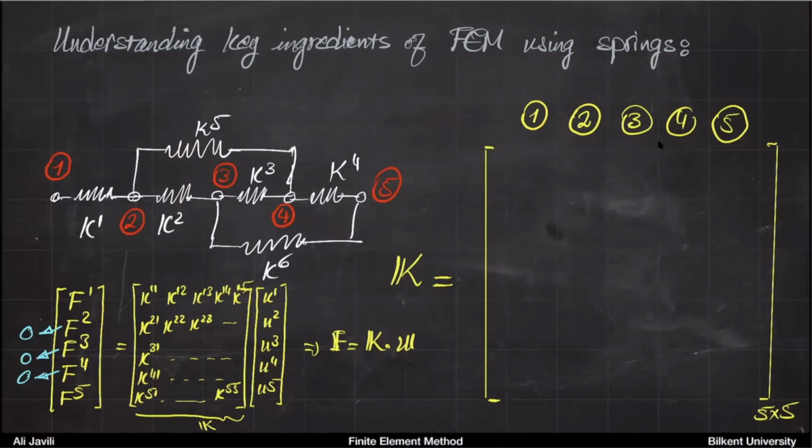What should we do? We should go, let's say, point by point, or we have two options, by the way. Either we go point by point, or we go element by element. Okay, so let's say you can come to this element, calculate its stiffness, and then enter where is appropriate. That's element-wise assembly.